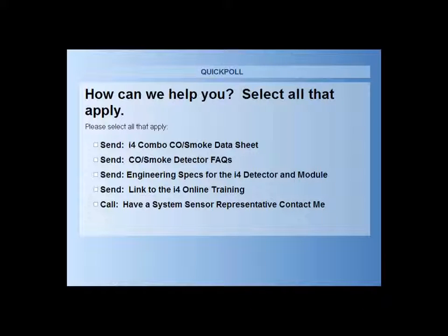Justin, you talked about a 10-foot rule. They're wondering, is that a code requirement or a general suggestion? So the detector within 10 feet of, say, some sort of steam or cooking or something like that. Oh, yeah, absolutely. That is definitely something that we're telling is an actual rule and a guideline. Any closer than within 10 feet, especially given steam or any other environmental issue, might cause a problem with the detector itself. So definitely keep things 10 feet away from any potential hazard.